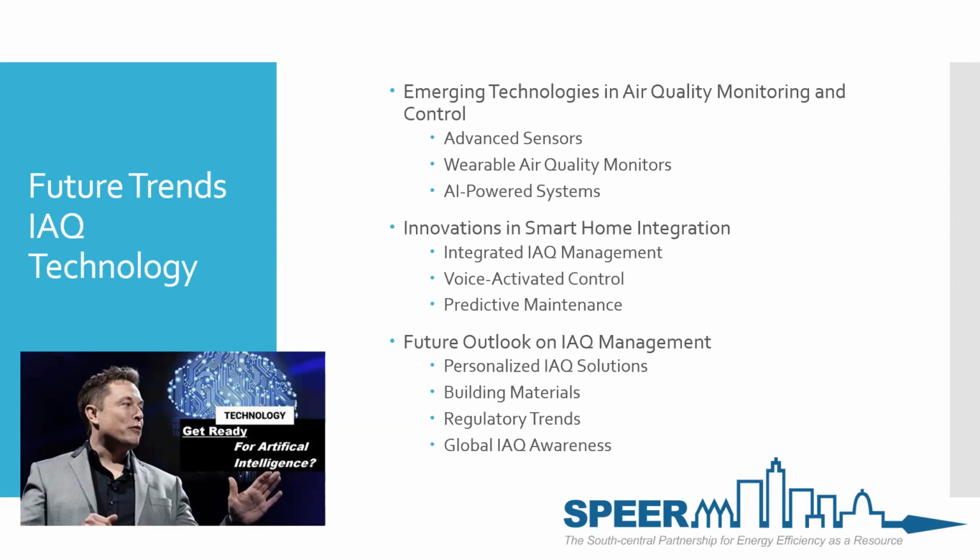An example of that is a smart ventilation system that is integrated with weather forecasts to optimize indoor air quality. So if it's a nice sunny day outside, and it doesn't have a lot of outdoor air quality issues, then it may turn outside air on and bring in more. And if it's raining, and yes, I know some of the systems now have humidistats, but if it already has the forecast that it can read, it knows tomorrow will be rainy. So maybe it will bring more fresh air in today, when it's sunny outside, and not do it tomorrow because it knows it's going to rain all day, or a chance of rain all day, with humidity at 100% or around 100%.